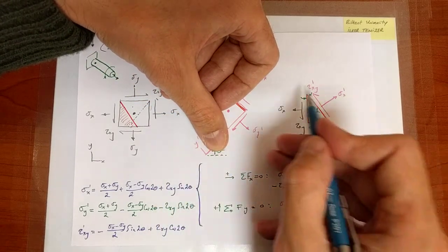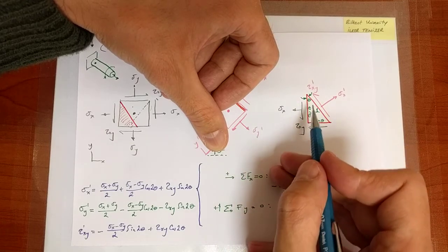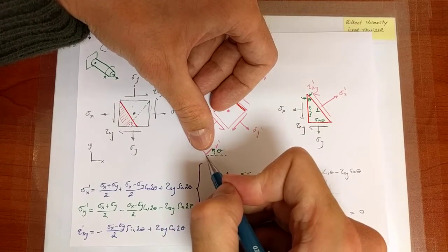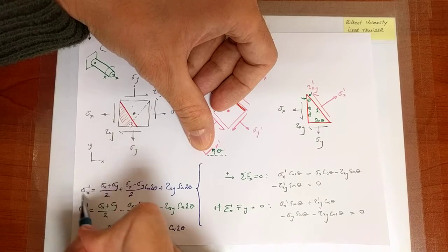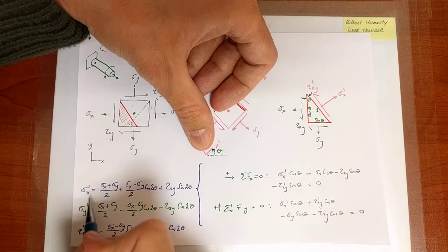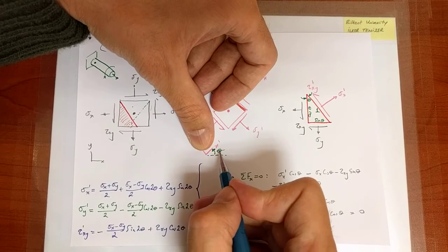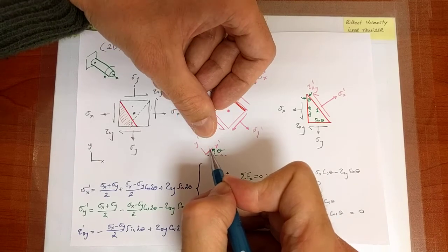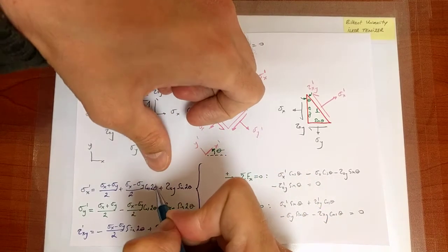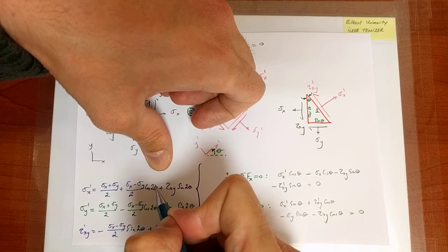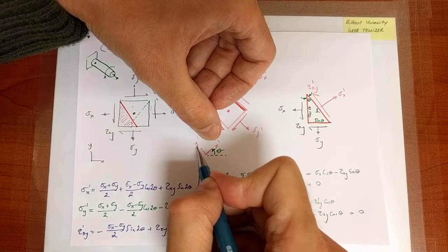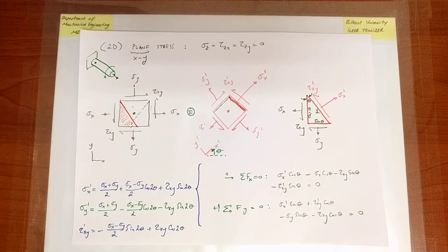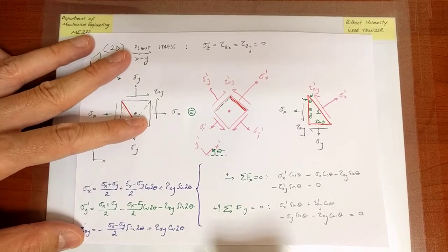So in other words, all of the calculations that I've done actually hold for an arbitrary value of theta, which means that if for a given value of theta I get an equation for the normal stress, which happens to be along x prime in my picture, then if instead of theta I plug into this equation theta plus 90 degrees, I will get the normal stress that lies along that direction, and hence the expression for sigma y prime. Well, let us see if that argument actually holds.